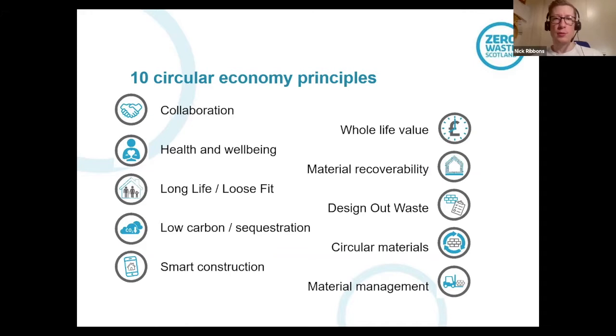Material recoverability, for example, designing in layers, was proposed, I think, maybe even before the 90s. I think Stuart Brand, an architect, proposed that. Understanding that the different layers of the building have different lifespans, and if you appreciate that, then you can design in such a way that you can maintain and repair your building with minimum fabric disruption, minimum disruption to occupants.